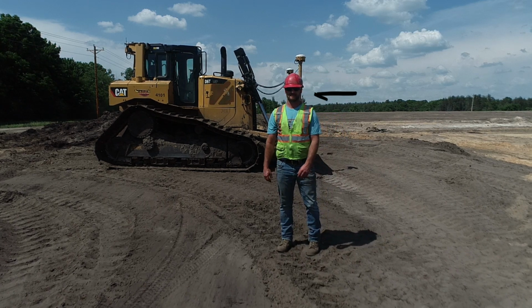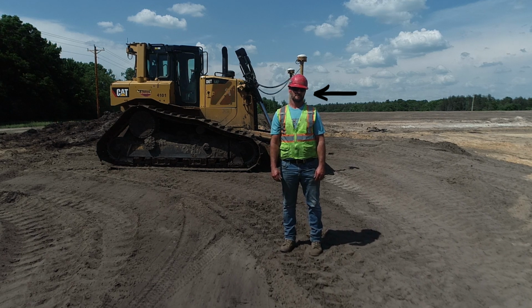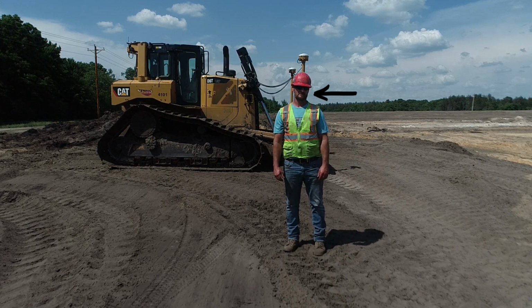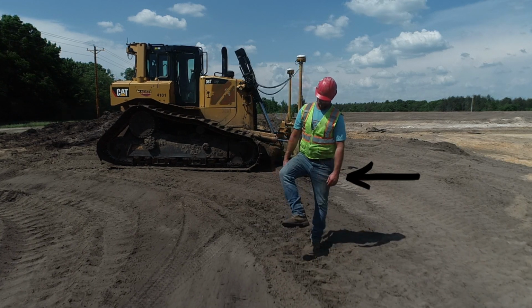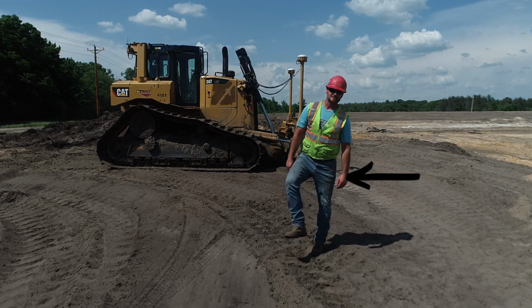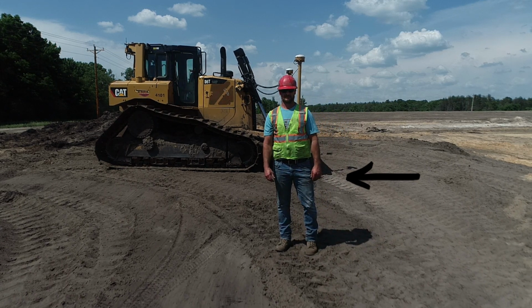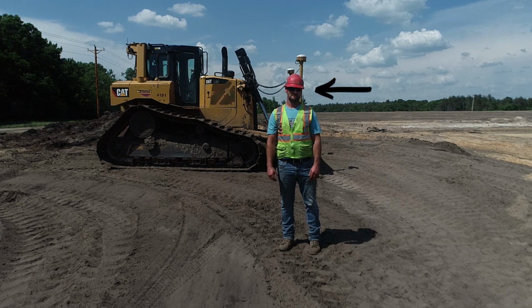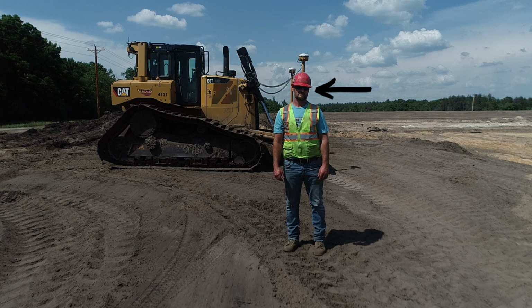Eye protection will be worn where there is danger of falling or flying debris from equipment or loads, especially in windy conditions. Hand protection will be worn when handling cable or any other material where there is danger of cuts or puncture injury. Hearing protection will be worn when exposed to noise levels exceeding 85 dBA.